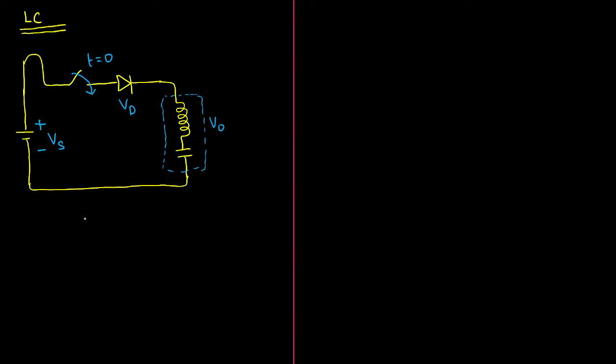So what I am directly writing is, if we observe the voltage drop across the inductor, it will become like this. The voltage drop across the inductor will be equal to the supply voltage into cos of omega t. Similarly, if you derive the expression for the voltage drop across the capacitor, that will be Vs into 1 minus cos omega t. This is an LC circuit. Remember, inductor and capacitor will be playing against each other, so they will be creating an oscillating waveform.